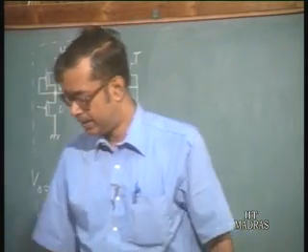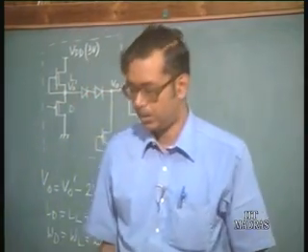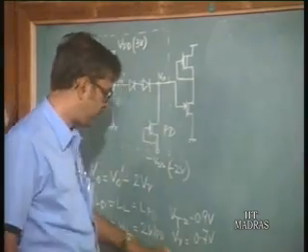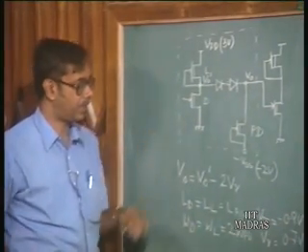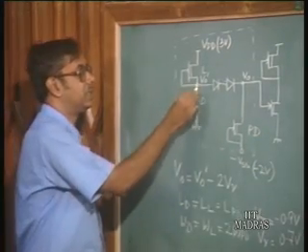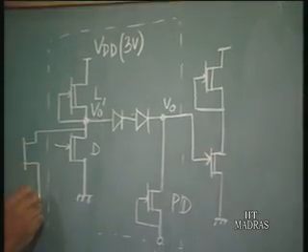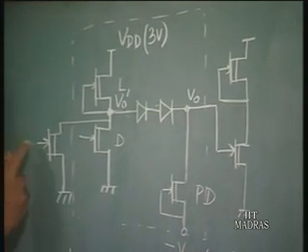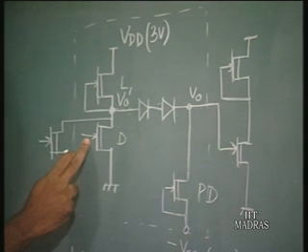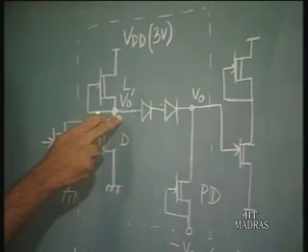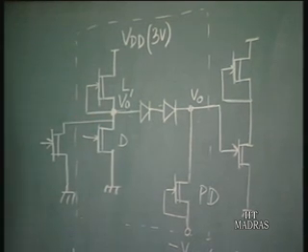So, we have seen the inverter structure for this particular logic and seen that its input output characteristics behave as an inverter. If we want to make a NOR gate from this inverter, we follow the usual procedure, that is we have another similar transistor in parallel with the driver transistor, and so when any of these two inputs are high, the output at this point is going to be low. So, it follows the NOR configuration.